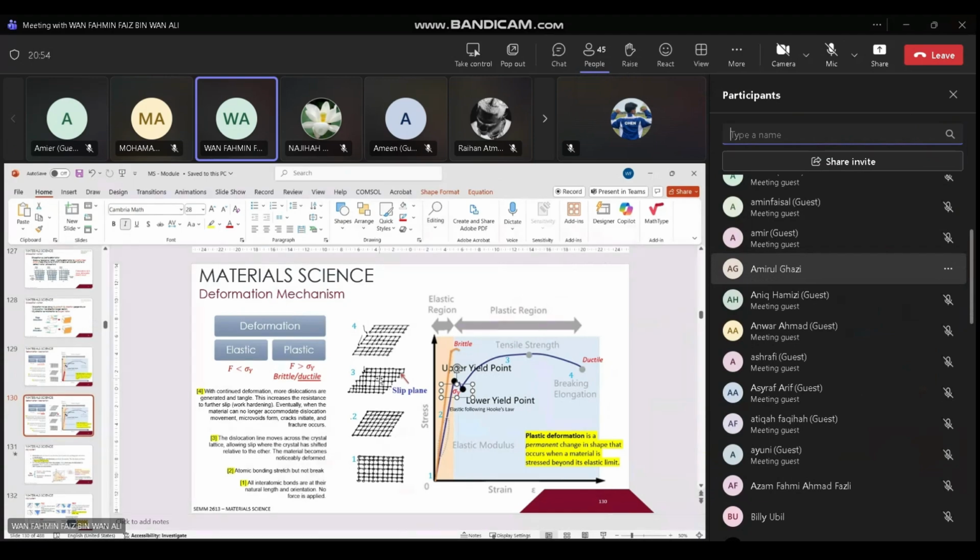Remember, it could be edge dislocation or screw dislocation, depending on the type of external loading that you apply. If you apply shear force, then you will have a screw dislocation. But since the graph is under tension conditions, we assume you have extra half planes, which is similar to edge dislocations.